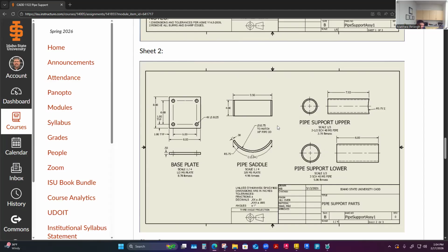If it's rolled, shops are different, I get it, but a lot of them have templates for different diameters, and they can quickly hold up a little pattern to see if they've either step broke or rolled this thing correctly. Especially where they're still manually operating machines and robots aren't controlling that stuff, which is still pretty common in the industry, a lot of manual operations.